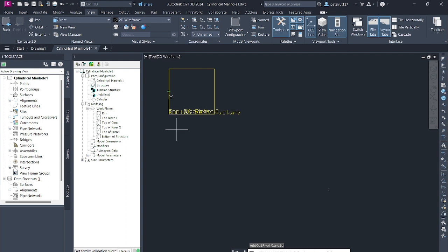Select Layout Data, right-click and then click Select Placement Point. The command line prompts you to select a placement point. Use your node OSNAP to select the point at the center of the rim work plane circular profile. A small, cyan marker is displayed at that location. This marks the structure insertion point. Save the part. At this point, it is important to determine how the new part reacts in a drawing situation.